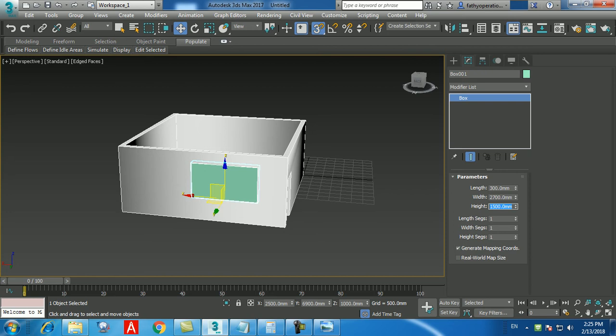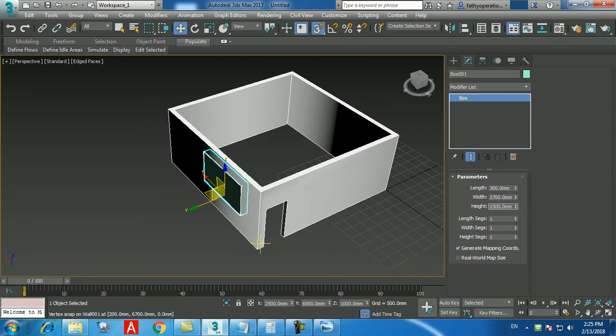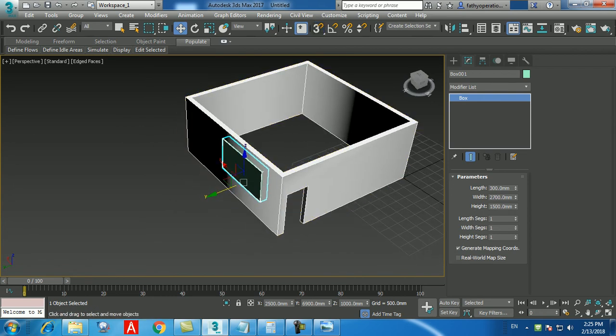Now don't do pro Boolean yet. Wait. Don't do pro Boolean. Okay. Now, before doing the pro Boolean, switch off the snap. Switch off the snap. If we keep it on, it will make it different. When you move it, it will be going here again. So better.